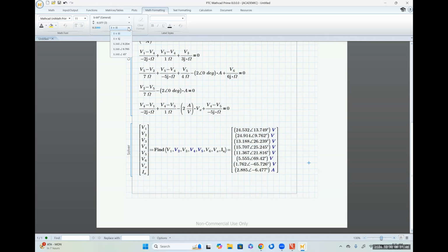It's very easy for MathCAD to interpret things in parentheses as a function of something else as opposed to a multiplication operation if you don't explicitly tell it to multiply. So that is the largest place that I see errors from you students is you don't tell it exactly, hey, multiply these two things, and it tries to interpret one thing as a function of the other thing.